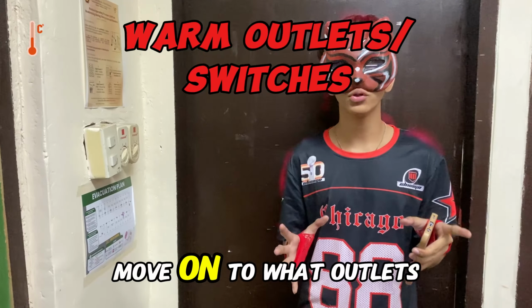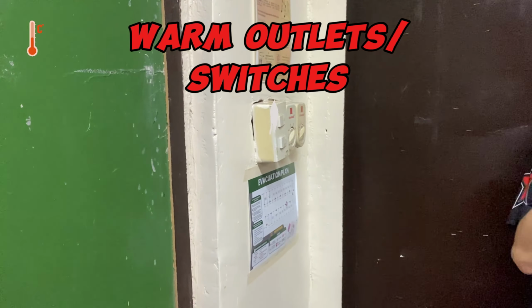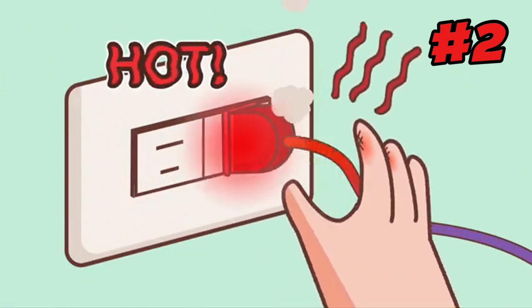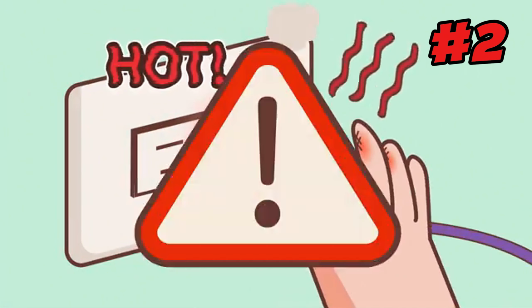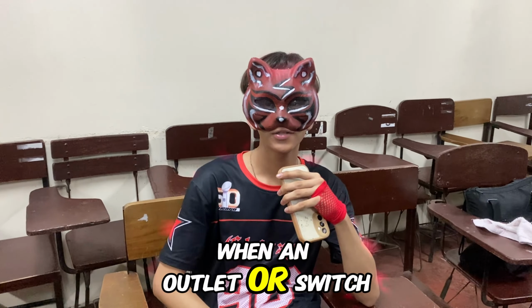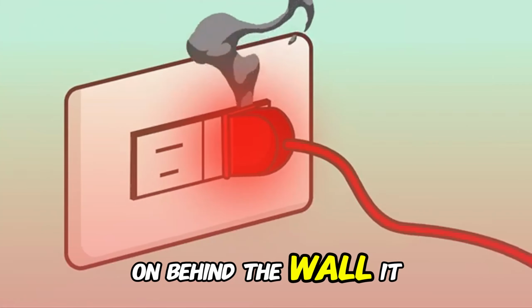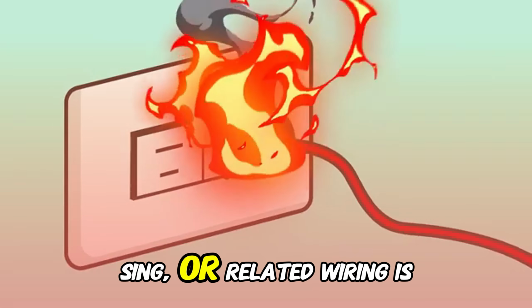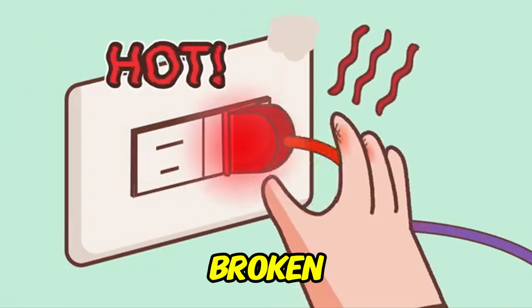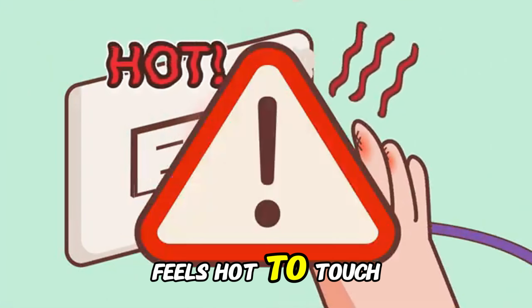Now let's move on to warm outlets or switches. When an outlet or switch is warm, it means something is going on behind the wall. It can be that the outlet casing or related wiring is broken. This could explain why your electrical outlet feels hot to touch.